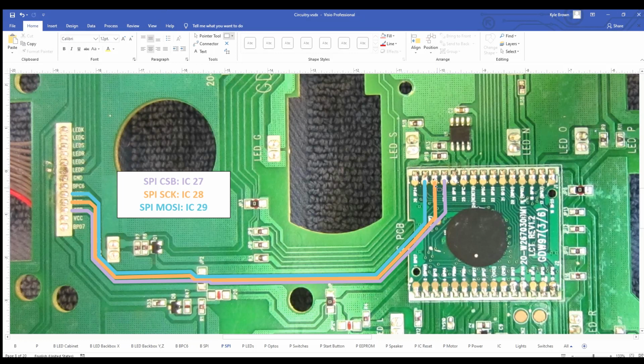I think if I wire the 2 boards together, I might be able to tap into the pins right here and use a microcontroller like an Arduino to output the data that's going across them. Then maybe I can figure out how the microcontroller is telling the Backbox to display different scores and to turn on and off LEDs.